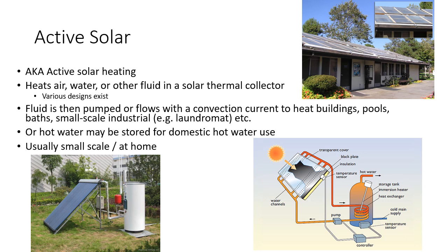Okay. A couple other things I should point out is that everything is painted black inside of these so that they collect as much heat as possible. And they're always going to be pretty well insulated, at least on the backside, so that it doesn't lose any excess heat that it gets. You want to use all that heat to heat up the water or heat up the air inside of it.